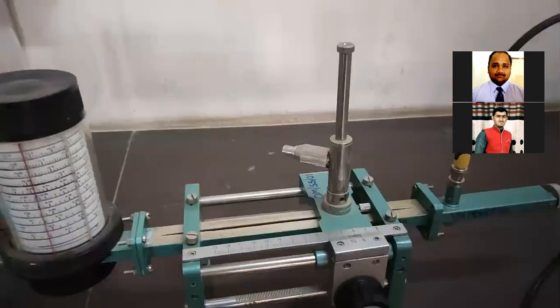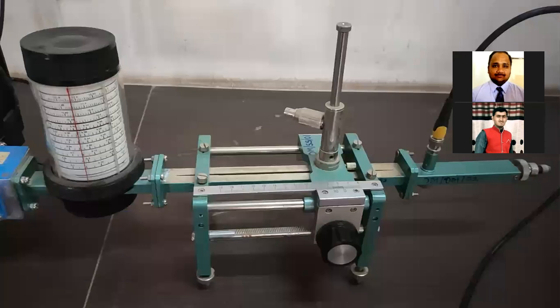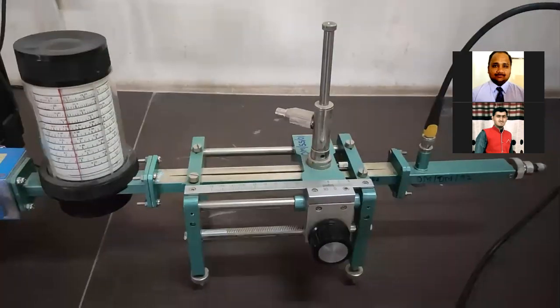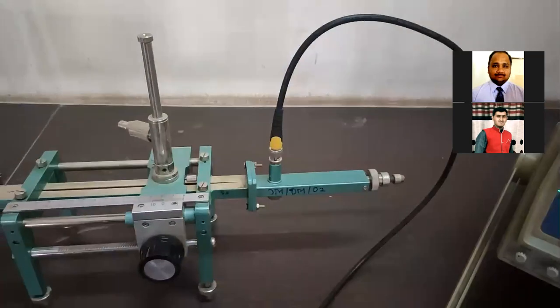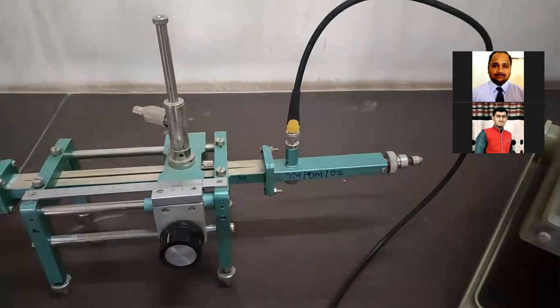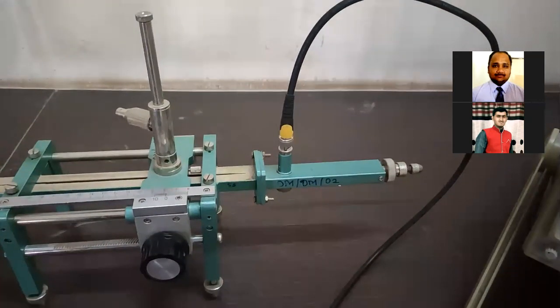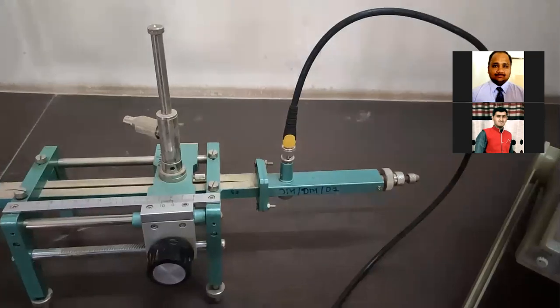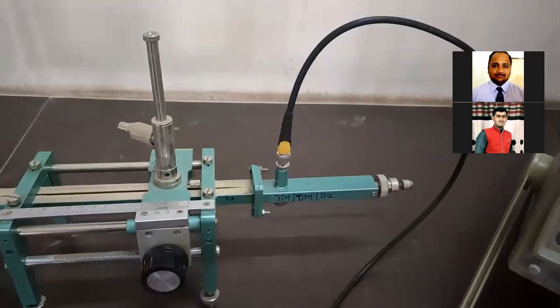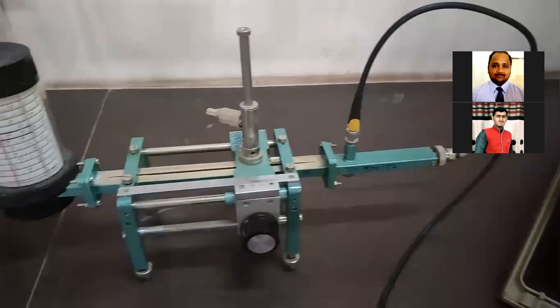After that, the next part of the microwave test bench is the slotted section, which is useful for finding VSWR of the microwave signal traveling inside this rectangular waveguide, and finally there is a match termination or microwave detector present in this microwave test bench. The last component is the detector mount, DM, which uses a Schottky barrier diode for detecting microwave signal, and then output of this detector mount is connected to a CRO. So this is a short introduction of the microwave test bench.